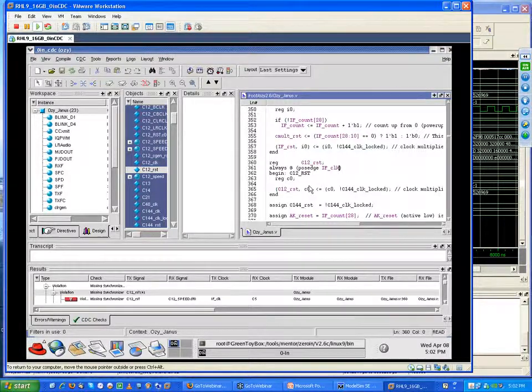Or what may have happened is I may not have had the prefixes on the signal. It may have had a different name with no prefix, and that's why I adhere to using prefixes when you're doing FPGA design work that has multiple clock domains, because visually you catch it. Without the prefixes, you're visually not going to catch it.